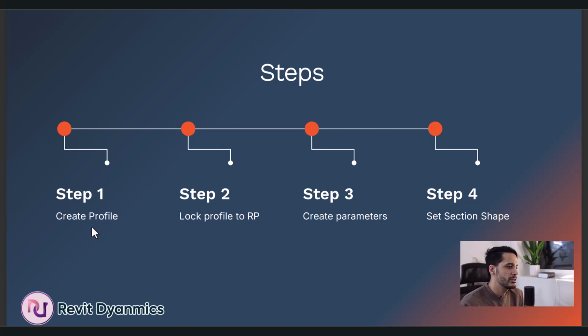For creating a structural framing or a structural column, we have two choices. The first option is to create the profile in the structural framing family, and the second option is to create the profile in another family, for example in a profile family template, and then load it to our structural framing or structural column family.